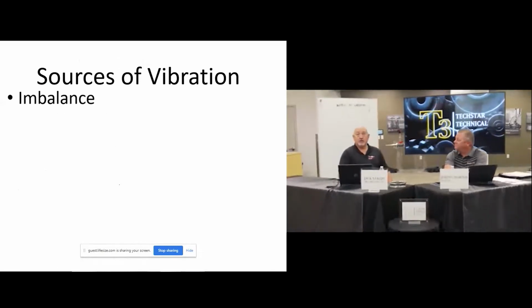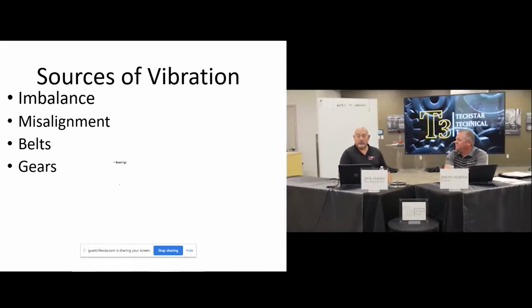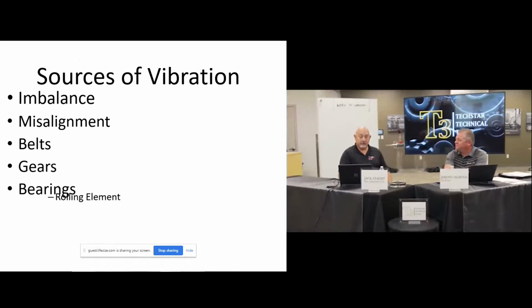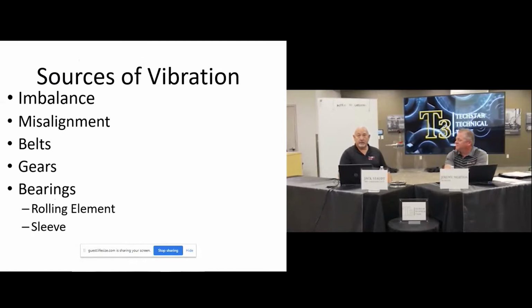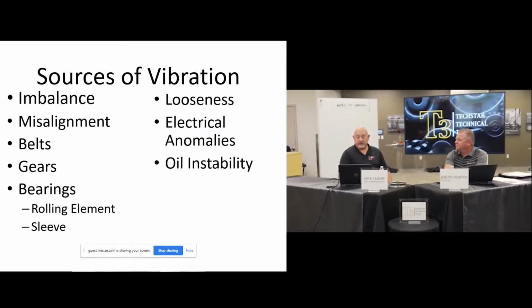But sources are imbalance, misalignment, belts, gears, bearings, rolling element and sleeve bearings, looseness, electrical anomalies, instability of the oil, and looking at resonance.